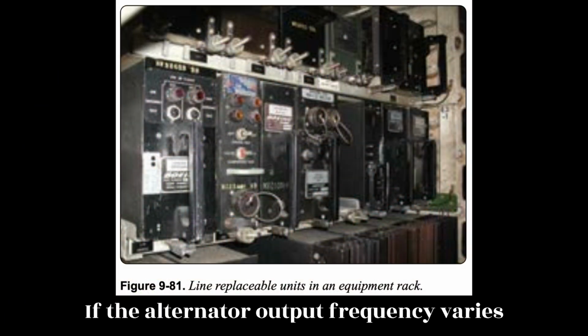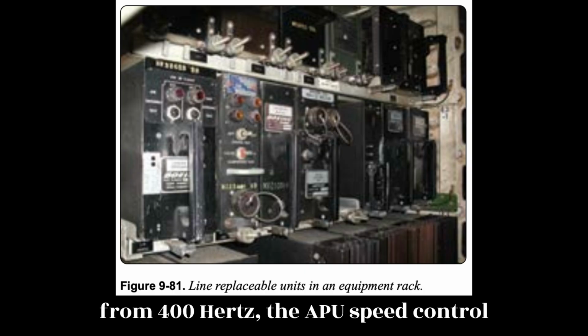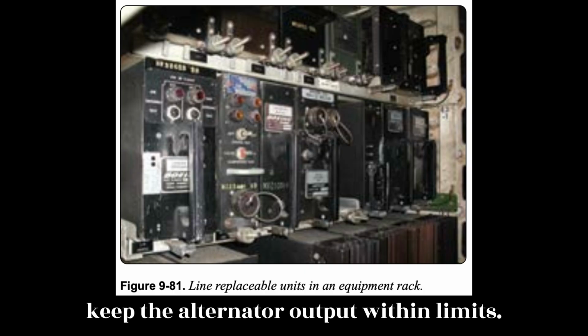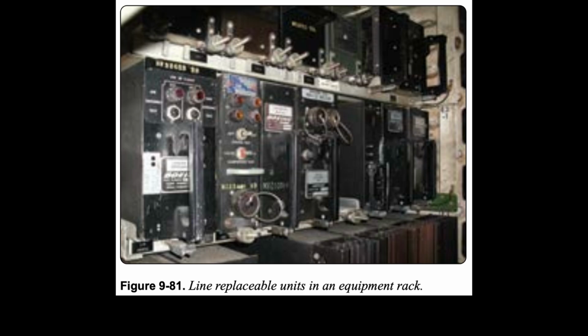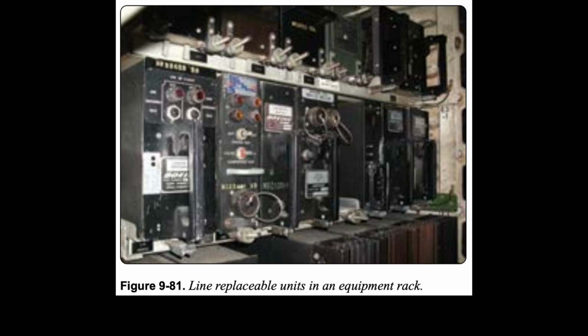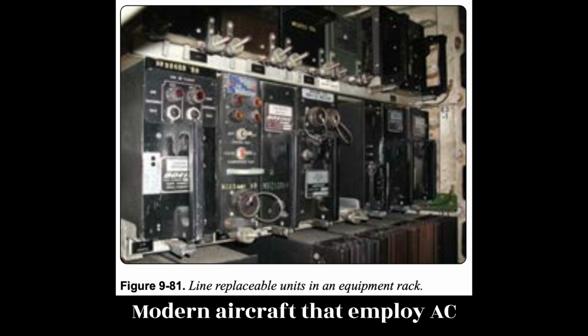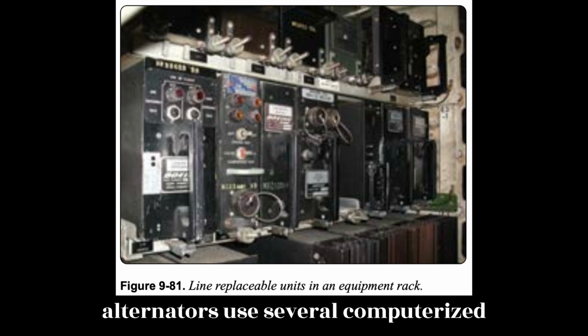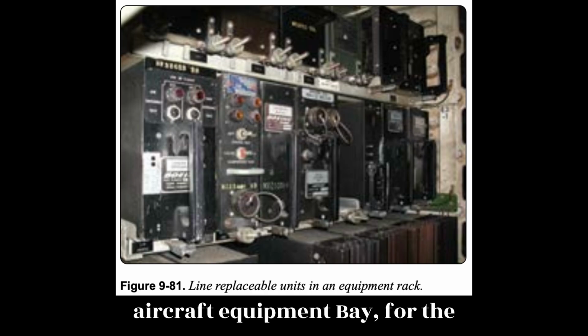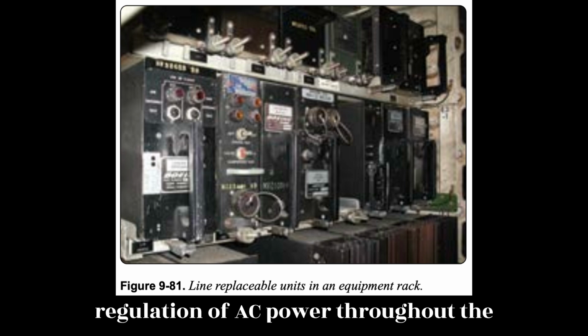If the alternator output frequency varies from 400 Hz, the APU speed control adjusts the engine RPM accordingly to keep the alternator output within limits. AC alternator control systems. Modern aircraft that employ AC alternators use several computerized control units, typically located in the aircraft's equipment bay for the regulation of AC power throughout the aircraft.